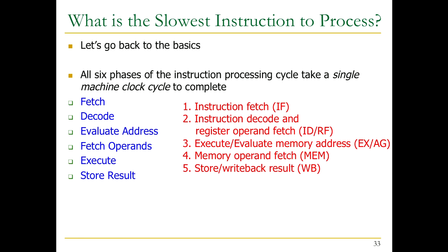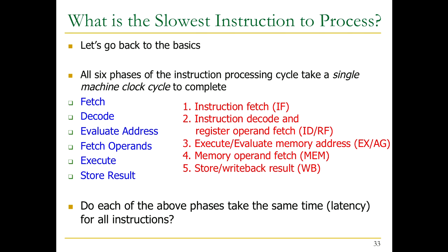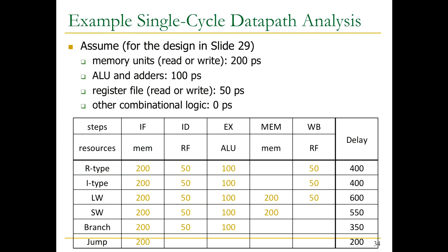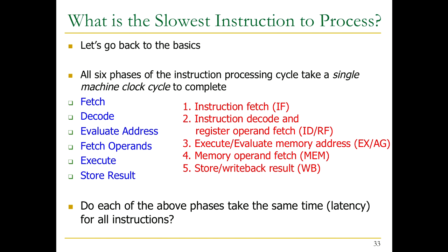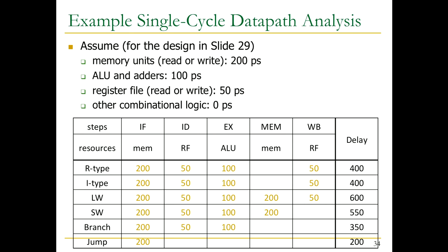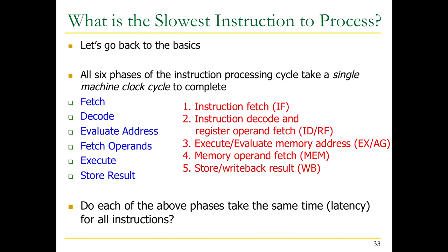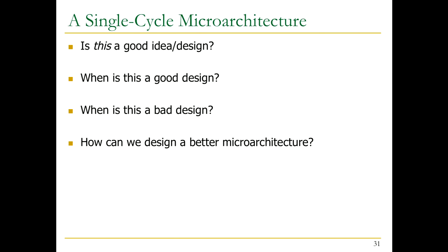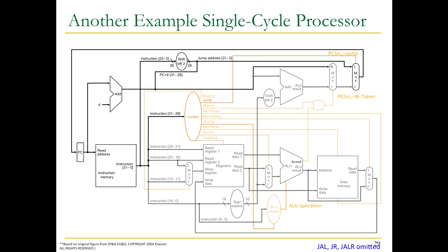Basically, different instructions go through these different stages, and I've collapsed them into 5 over here. One question is, do each of the above phases take the same amount of time for all instructions? Well, that's not necessarily true, actually. But let's assume some time for different instructions. This is based on the slide in the Patterson and Hennessy book. Again, you don't need to know exactly how this design is, but it's very similar to what you've seen last week.